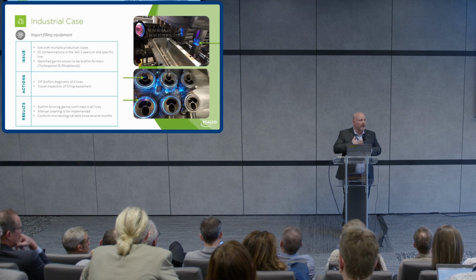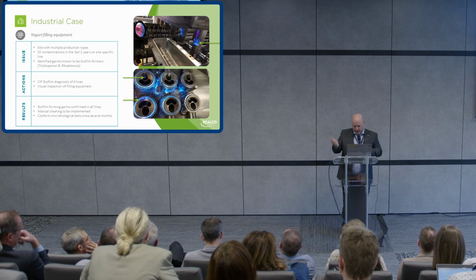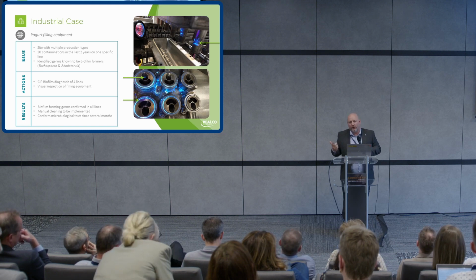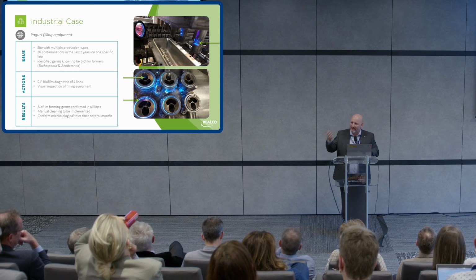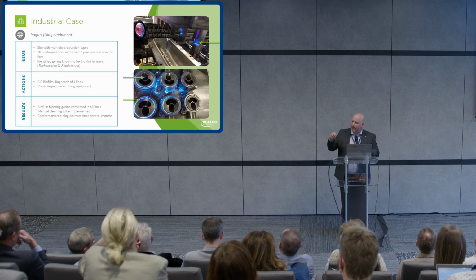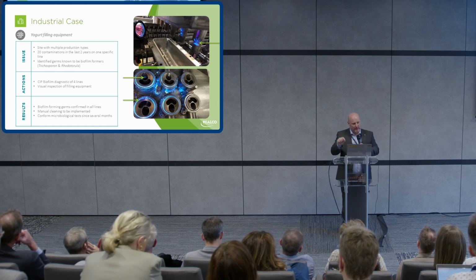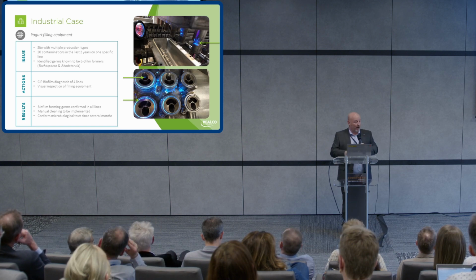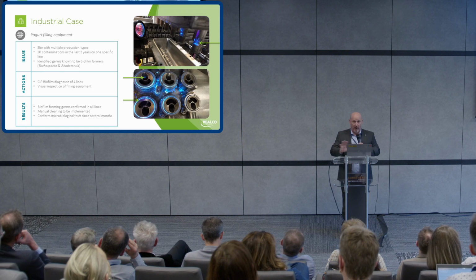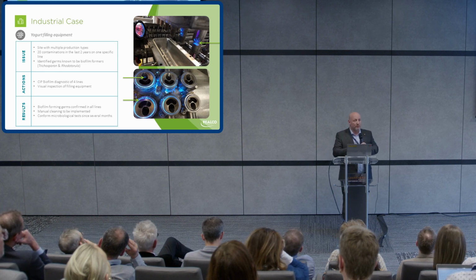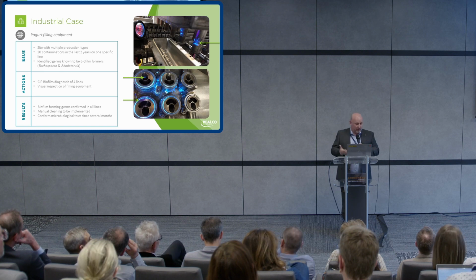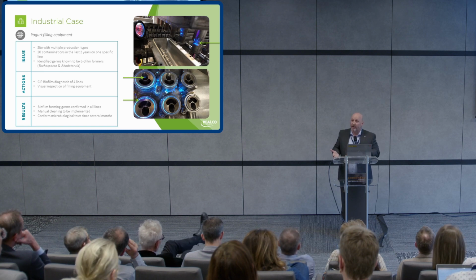So I'm not saying that every time biofilm is there, you cannot cope with good cleaning and good equipment. But sometimes you miss one piece of information, and if you do an investigation, you can understand, okay, this is where I have the issue, and I have to understand why this issue is still present. And sometimes it's a question of hygienic design. It's not a question of biofilm that resists cleaning. It's because the design is not okay, so the cleaning is not okay.